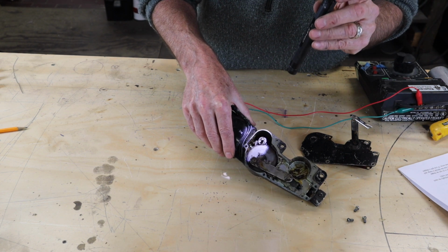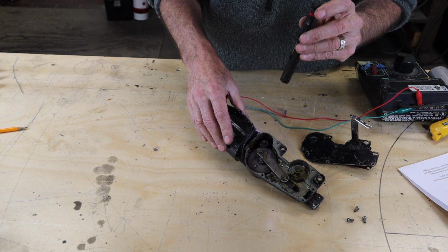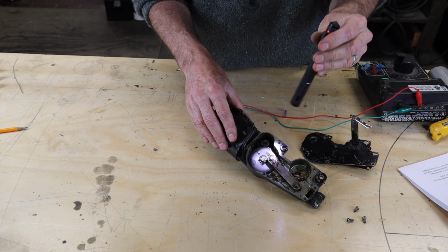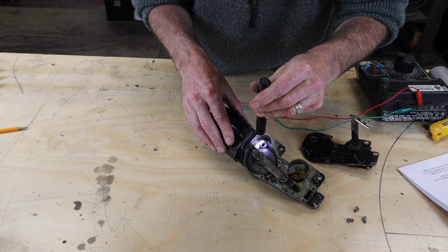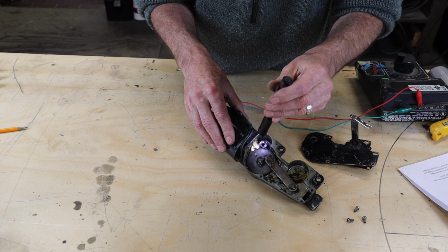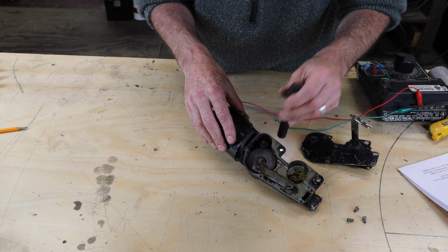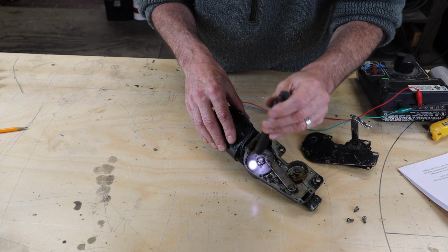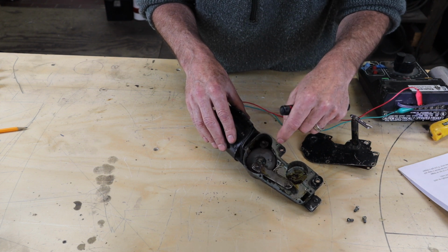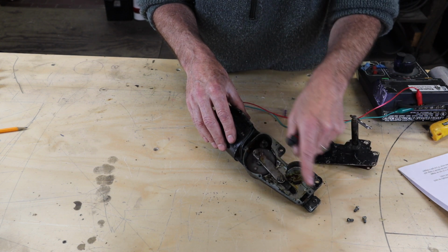So, you may not be able to see this because it's way down in there, but first off we have a worm drive. This motor has a shaft coming out like this that is spinning around. It is rubbing on the side of that small gear here, which is going reasonably fast. In a worm drive there's a worm on the shaft of the motor and the cog is right here. Then it goes to a gear reduction from small to large. So this is going probably 4 times as fast as this is. And then we end up with a crank slider mechanism because we want the back and forth motion.